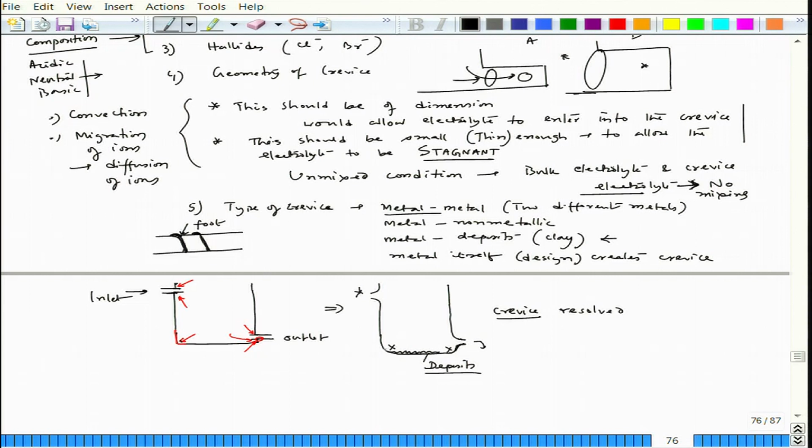But still you will see that a small amount of water up to the edge will remain, and that makes cleaning difficult, in the sense that somebody has to go in and clean everything. You cannot use any mechanical equipment, and even if you do, there will be a possibility of water logging. Otherwise, you have to wait a long time for the water to evaporate, and for a large tank even that residual water could be a huge amount. So, the best design to avoid water logging during maintenance or cleaning could be one like this.